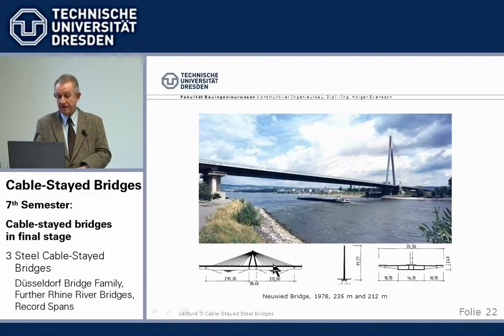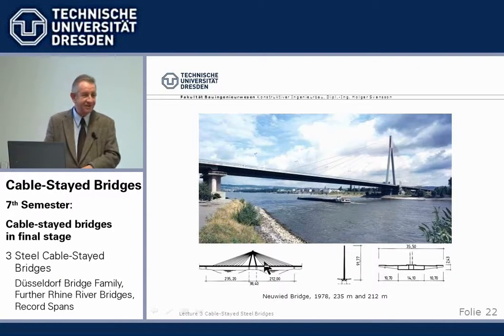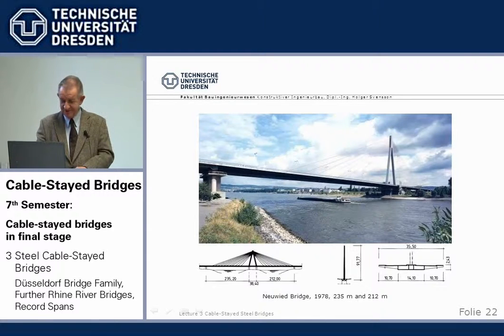And so a load here goes up, runs up the cable and is split in tension and compression and goes down directly into the foundation. We have some more examples, and I think the examination last or the one before the last, I asked to calculate such a system with the forces in the tower legs. But we had prepared it in the repetitorium before.